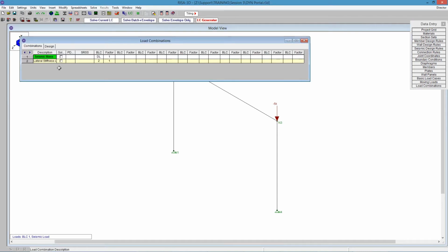It's really important, in order to create your dynamic model, that you need a load combination using your seismic mass. So it's always a good idea to do a separate load combination to understand just that seismic mass. Oftentimes people go with a conservative route and over-apply dead loads, things like that. But when you're using seismic mass, you want to go exactly with what you've got listed there for the mass. You're not going to apply anything but your mass in that load combination, and that is what we use to define the dynamic analysis and find the mode shape.